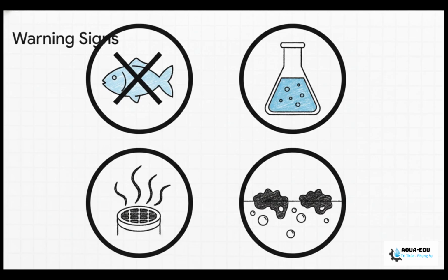Obviously, if your total nitrogen exceeds your limits, or if your nitrite spikes over 1 milligram per liter, which by the way is highly toxic to downstream fish, those are massive red flags. But what about physically? Well, if you start seeing cloudy, light blue water, or if you catch a really foul, unpleasant stench, or, worst of all, if you see sludge floating with trapped nitrogen gas bubbles out in your secondary clarifier, your denitrification process is severely interrupted.